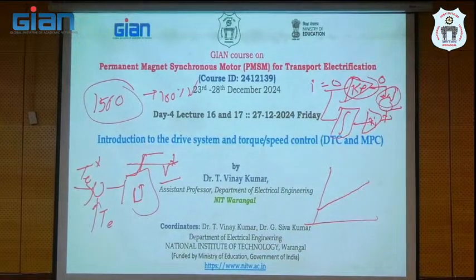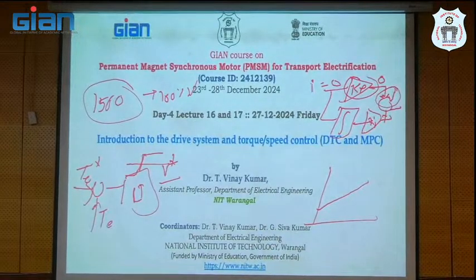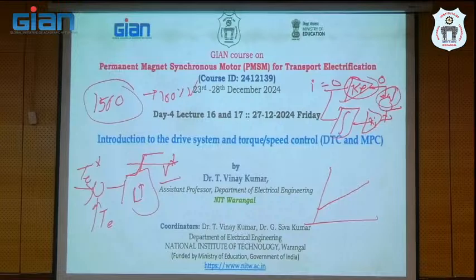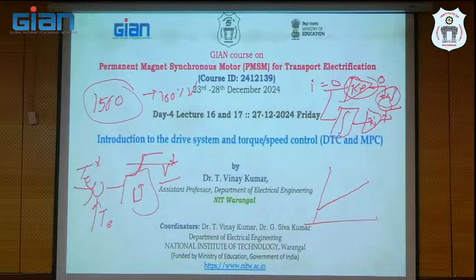But the P controller is based on the current instant. The integrator will work based on the current and past instants. Adding derivative, it takes the difference between the current and previous state. The integrator will add cumulatively, right? So all these are the fundamentals.